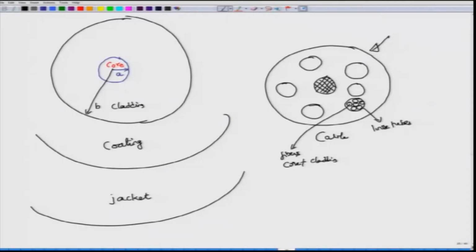Of course, the cable also has additional things than just holding the fibers, it also gives all the fibers a mechanical support, right. I mean, you might lay a fiber cable underground crossing one road to another road, but then you have a concrete road on top of it where the vehicles actually keep moving, then if you just had the fibers below, these fibers would not be able to take that mechanical stress, they would just break. So, instead, if you encapsulate them with thick cables, these cables themselves are encapsulated in bigger cables. So, you do need to take care of all those issues, because you want the fibers not to break, because you have to use these fibers for communication.